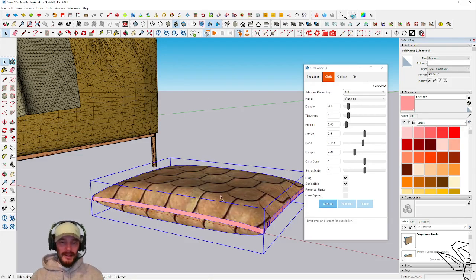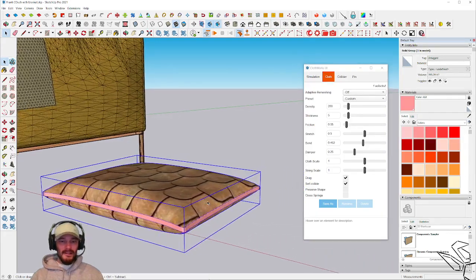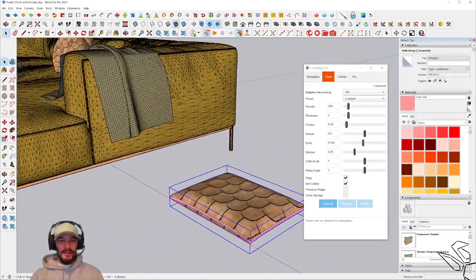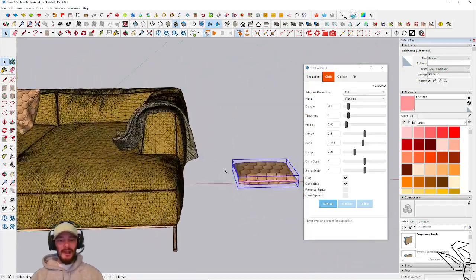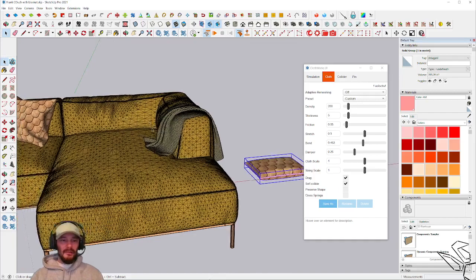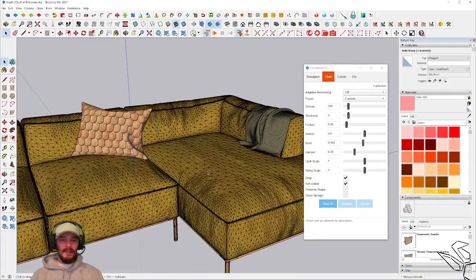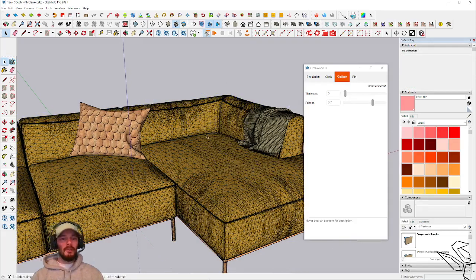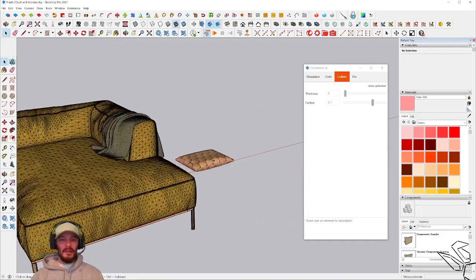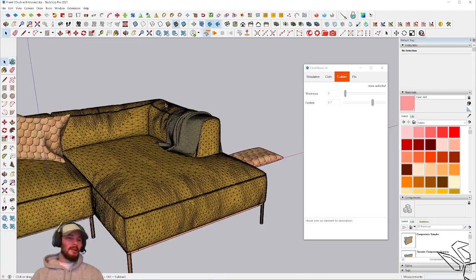Look at that. It inflated it. The texture stayed intact. And all in all, that looks pretty good. Now the next thing you can do is take this and angle it and position it, bring it over here, and tell this couch under ClothWorks that it's a collider, something to collide with your cloth, and then drop your cloth, the pillow that we just created, right on top of this couch.